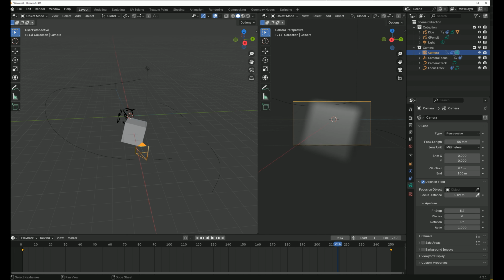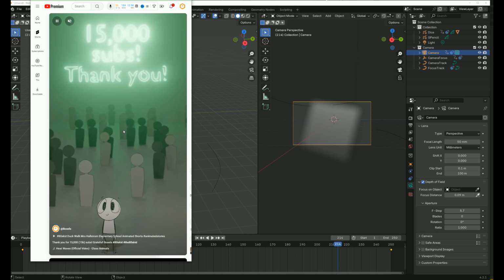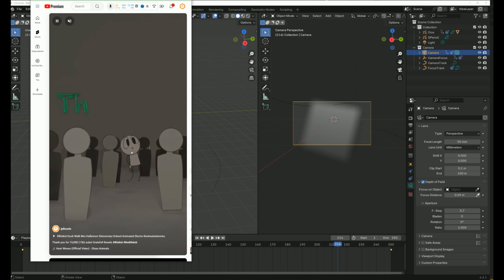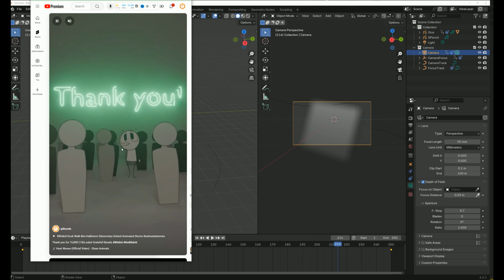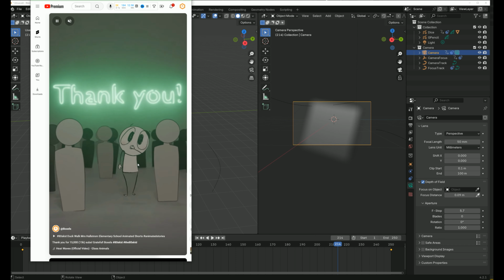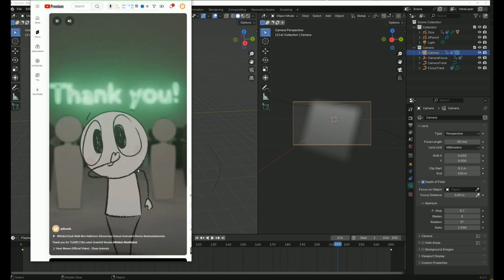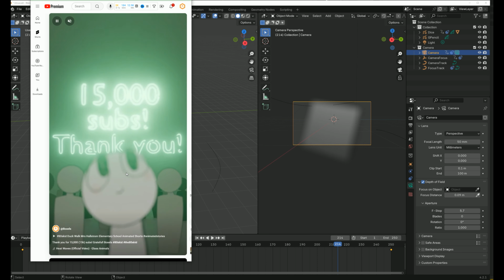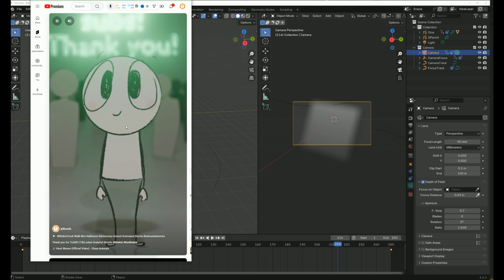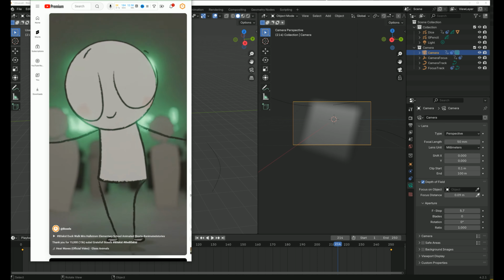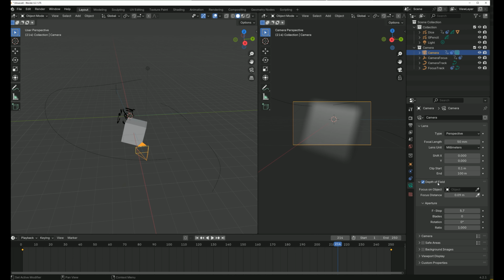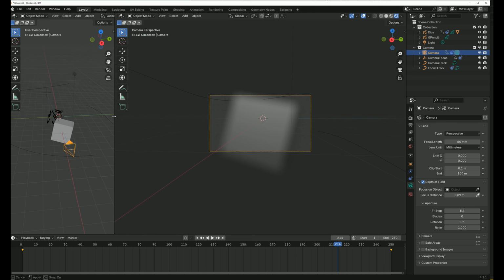That is this effect that I did just real quick on my video here, where you can see the background characters. Well, if you looked real fast there, I was blurry at first, and then my depth of field changed. And what I did is I focused on an empty behind my character and just moved it where I wanted the camera to focus. And there I'm blurry, and this is focused, and now I'm back and focused, and the background characters are blurry. So that's what this is here, is this depth of field. And you can marry it to an object. So I could click this and go to my camera focus, or you can just frame it here, hit I. I'm going to undo that. And as you can see here, in order to see this, you've got to be in render view rather than just your object view here.